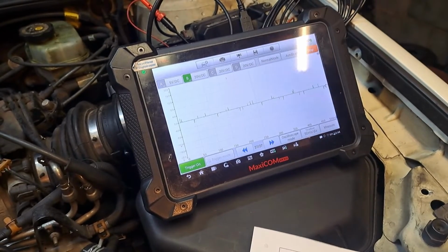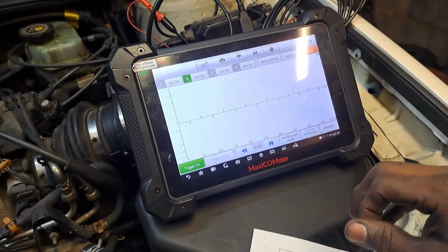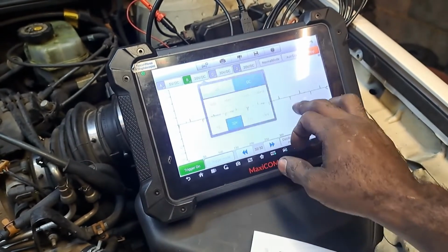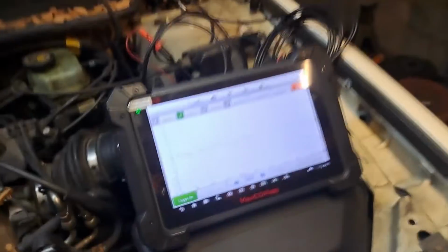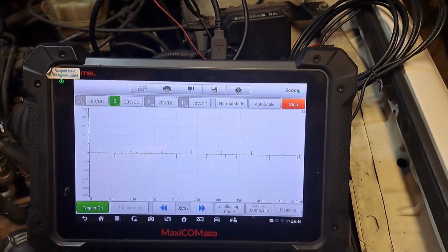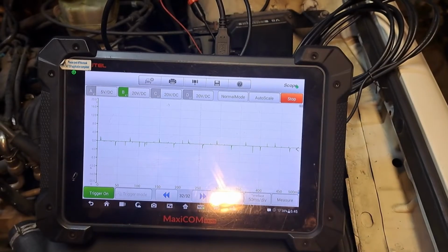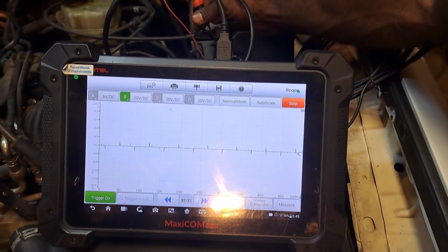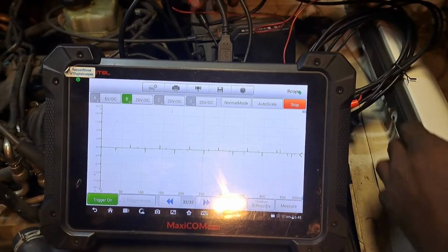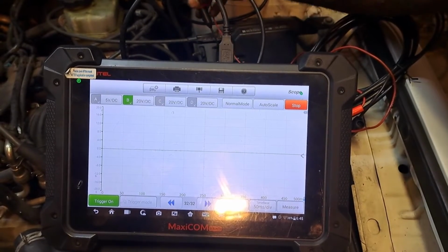It's going 10 miles per hour. And what's up with this? What did I do wrong? I don't have vehicle speed here. Strangely, I don't have vehicle speed, unless there's something wrong with my connection. Let me test my system. Oh, you know what? The reason it's not working is because I don't have my ground hooked up. Duh.